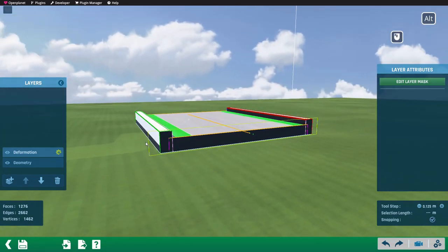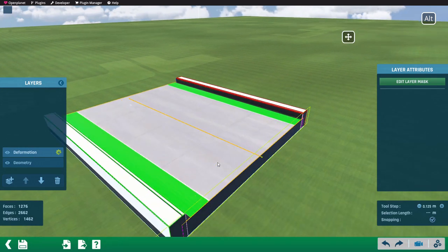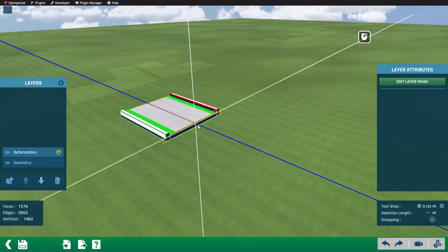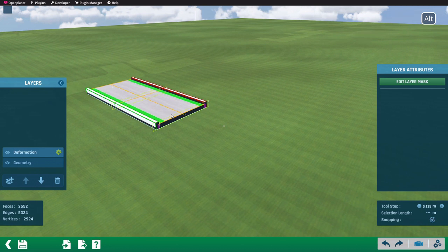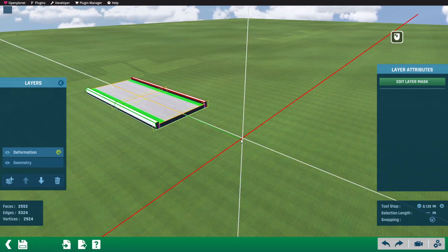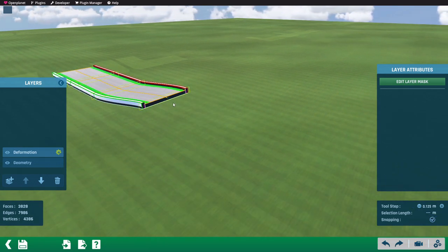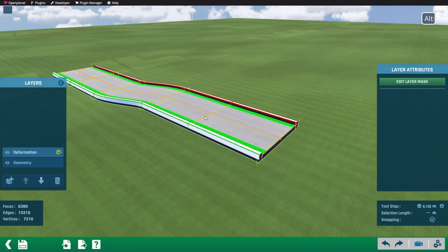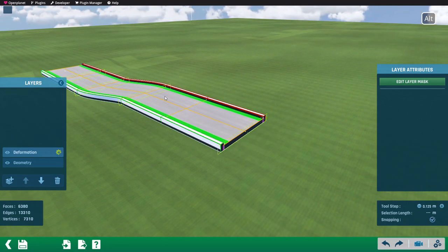Here's how this layer works. The editor calculates a spline by following control frames that you can manipulate. As you adjust these control frames, the item will deform along the spline, allowing you to sculpt and shape it according to your preferences. There are 5 options for editing the deformation.